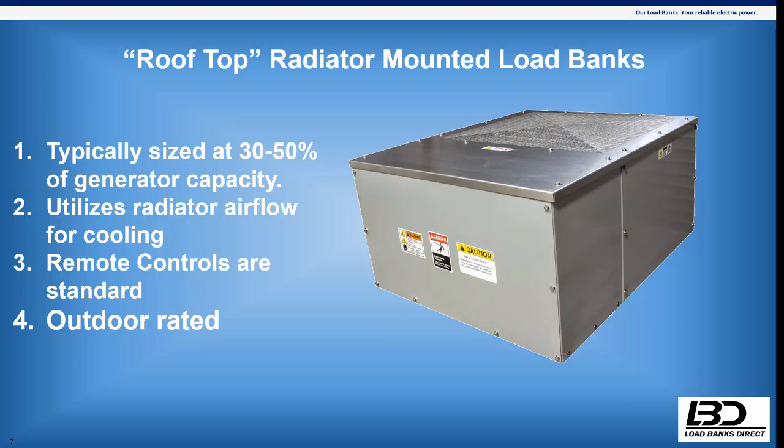But it's the very same exact concept, except these are outdoor rated, the same general size, 30 to 50% of your generator capacity, because it's still utilizing the cooling airflow from the radiator. It's just typically vertically exhausted out the top of the enclosure.